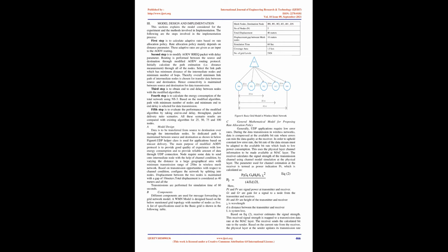In the simulation process, basic energy source is considered for energy consumption calculation. Operation: basic energy source stores some initial energy value, that is 0, and a sample of total current draw at the node with time. When Wi-Fi radios change their operating state, basic energy source is notified and the new current value, I(t+1), within a time t+1, is calculated by using basic energy source objects such as calculate total current. Supply voltage V is taken.